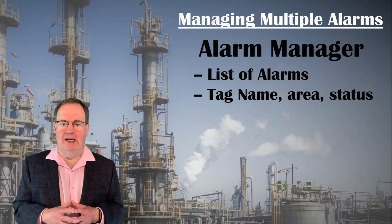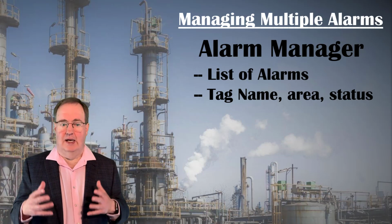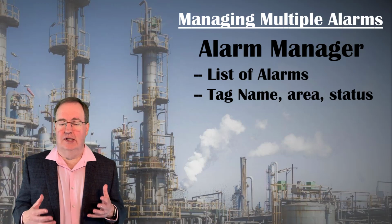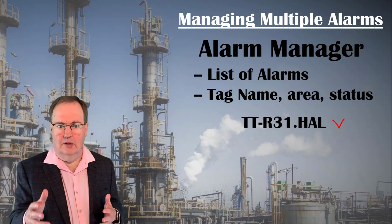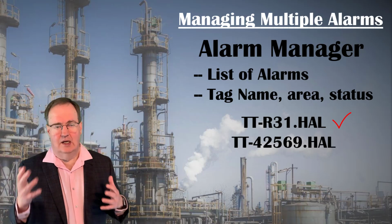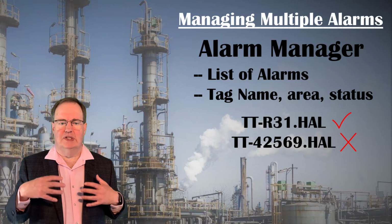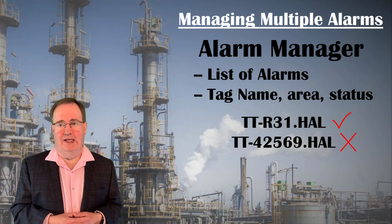It helps if the plant has a descriptive tag numbering system, so that high temperature in reactor 31 is recorded as TT-R31.high alarm rather than TT-42569.high alarm. But the list of alarms in an alarm manager is more often useful in postmortems than in the heat of the moment.